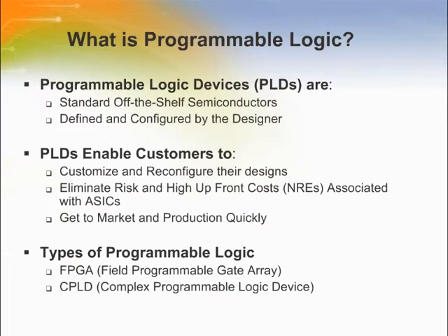Programmable logic is loosely defined as a device with configurable logic and flip-flops linked together with programmable resources that control the interconnections. User programmable memory cells control and define the function that the logic performs and how the various logic functions are interconnected. Thus, a wide range of sequential circuits can be implemented on a low-cost PLD. Though various devices use different architectures, all are based on this fundamental idea.